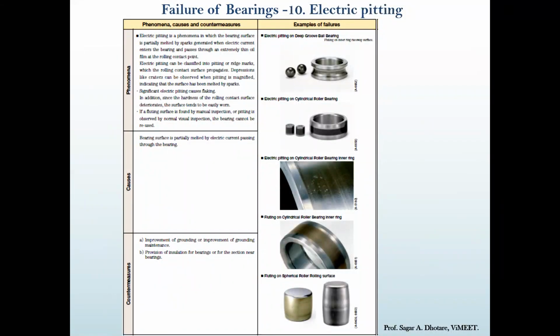The reason for this kind of failure is that the bearing surface is partially melted by electric current passing through the bearing. Only because of this can this kind of failure occur. You can look at the figures and understand the phenomenon.